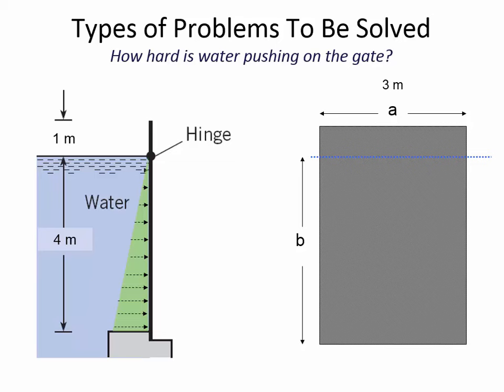I've already maybe given you a hint, but here's the pressure, right? We want to find out where it is that half of the area of this triangle is above it and half of the area of this triangle is below it. 1/3, right. It's 1/3 from the bottom, so 2/3 from the top. So that is the center of area for the pressure distribution, right?